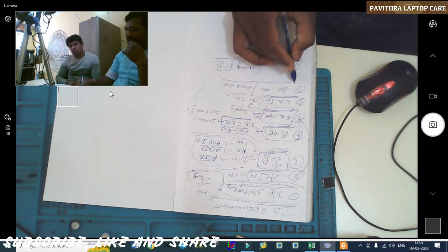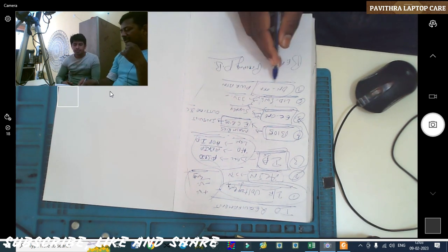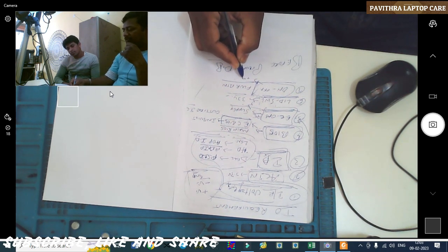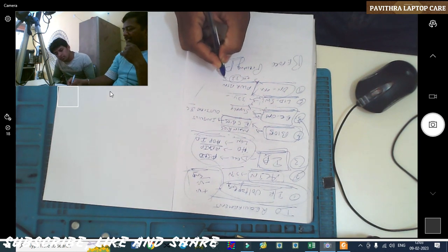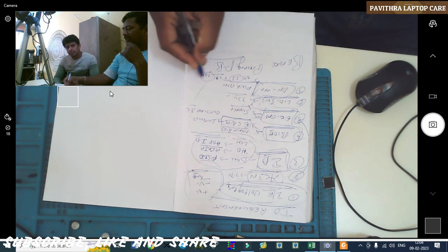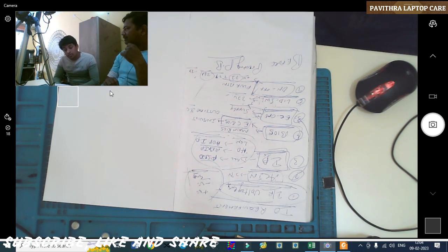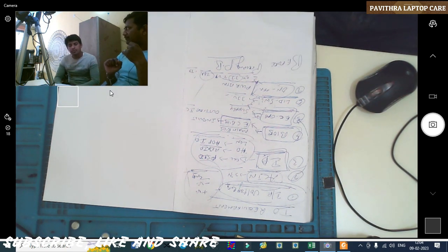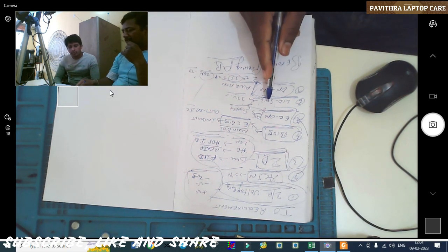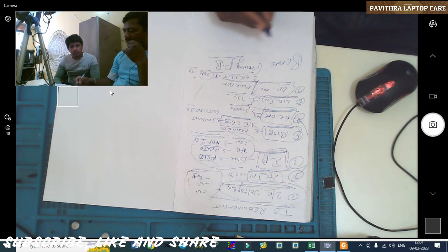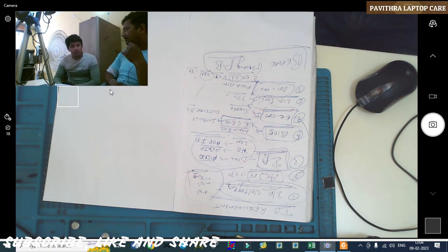Okay, next one is on and off. This is a very important thing. Here in the on and off button, one side is positive volts, meaning 3.3 or 3 volts or 2.9 volts. Sometimes it may be 28 volts also. When you press, it becomes 3.3 volts. There is also a logic there that I'll explain in future. This positive voltage should be there on the on and off button. This we also have to check. The lid switch and on and off will be together, and we need to check that thoroughly. This is the condition before the power button.